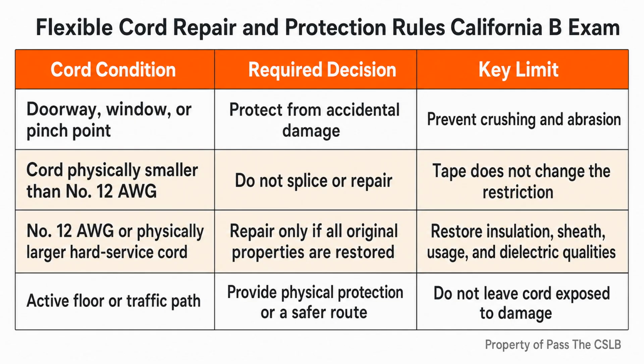The condition matters more than the slogan. "Portable generators never need grounding" is too broad. The exception depends on what the generator supplies and how the receptacles are bonded. When the setup falls outside those conditions, I do not extend the exception by habit. I verify the applicable requirements for the actual configuration.